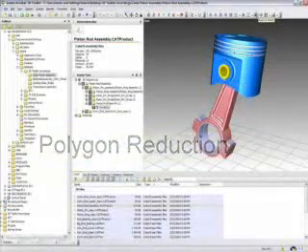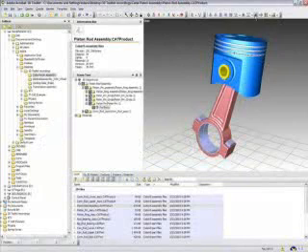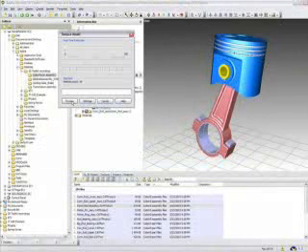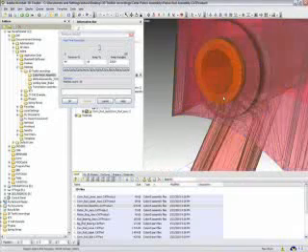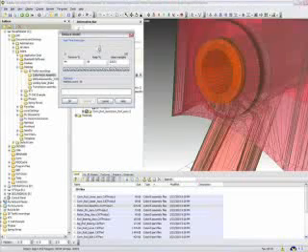With nothing selected in the viewport, I click the Reduce Model tool. In the dialog, I select Process to analyze all the meshes in the scene. Once this is completed, I can dynamically reduce the number of polygons by using either the slider at the top, by clicking any of the percentages, or by typing in the number of triangles or percentage of triangles I wish to keep in the scene. The slider dynamically displays the 3D mesh reduction in the viewport. If you zoom up on a part, you can view the polygon change as you change values.